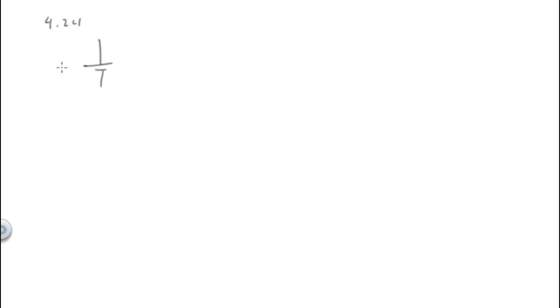I've got 10 volts and 50 ohms up here, and then I'm going to put various resistors across here: 0, 25, 50, 100, and an open circuit. In each case, when I hang a resistor of some value, I have to find the I or the V, and then do the I squared R or the V squared over R.